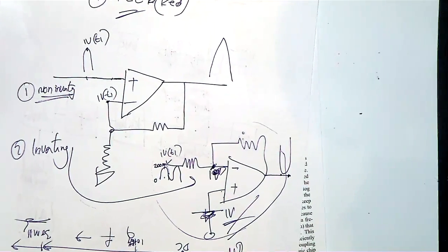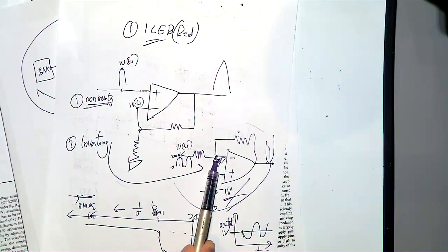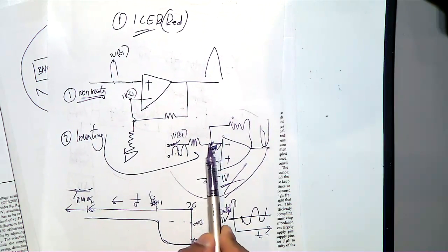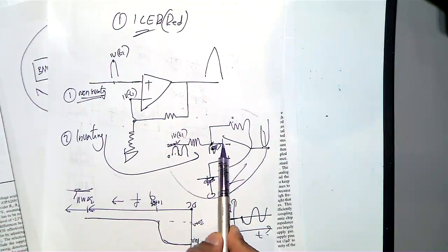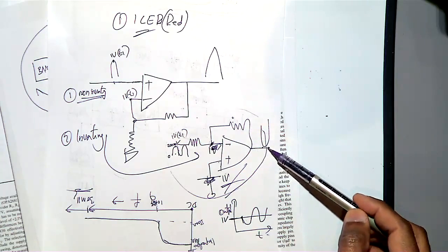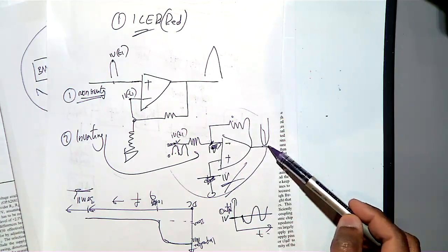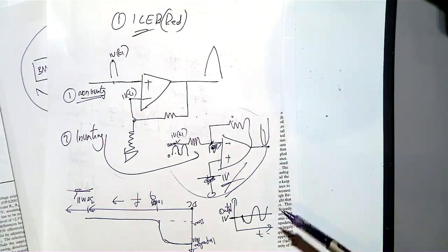So it is a level shifter and amplifier, because when you plot the output, your output will be offset by 1 volt, because when this is 1 volt, this will become 1 volt, and then when this is 1 volt, nothing will go, current will not go through the operational amplifier, and then this 1 volt is connecting through the resistor and coming here. So you are getting a DC 1 volt, then this signal will be amplified, that also is coming through here. So that is the reason you are getting a level shifting.